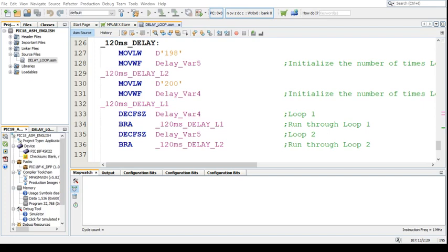Keep in mind, if you want a delay of less than 150 milliseconds, you could use 3 loops for that. Just keep in mind that your accuracy is going to be really off. It's not going to be great, your accuracy levels with regards to the delays. So what I mean is, you could change a register, like in this case, you see 200 there. If it was 3 loops and you changed it to 201, your delay could jump by actually 10 milliseconds.